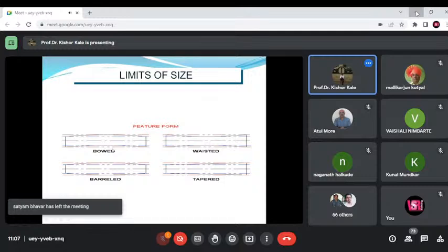Now this surface should be parallel to A. The variation should be 0.005 with respect to A. And this says that whatever the angle is with respect to B, here the angle is given as 20 degrees, it should only vary by 0.005 degrees, not more than that. So this angle will vary with respect to this B datum. This is angularity, and this is parallelism. I hope you are able to understand. So this is how datums are important here.